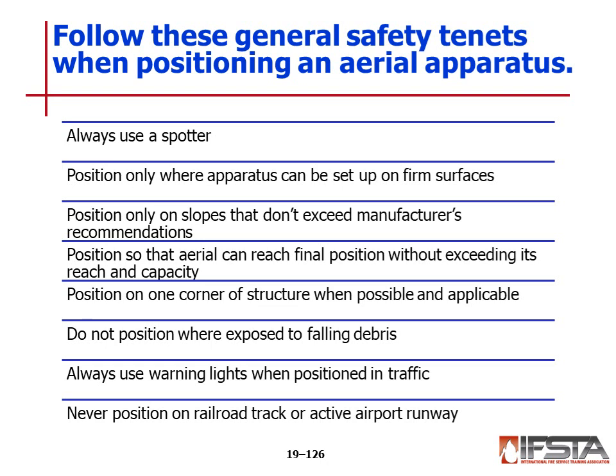Do not position where exposed to falling debris. Always use warning lights when positioned in traffic. Never position on railroad tracks or an active runway.